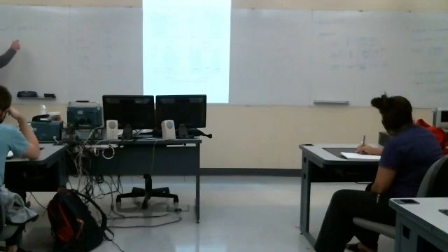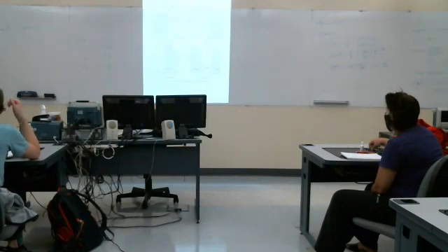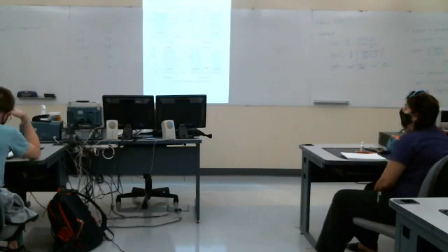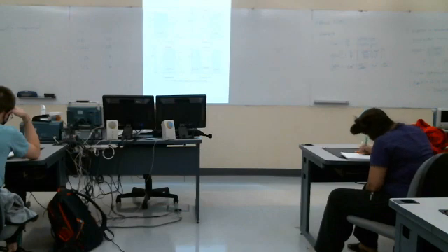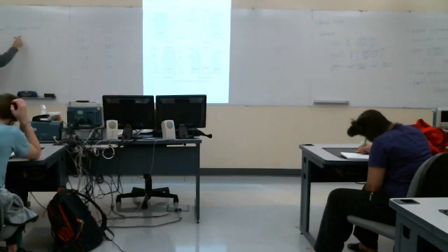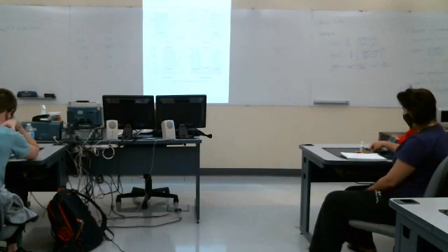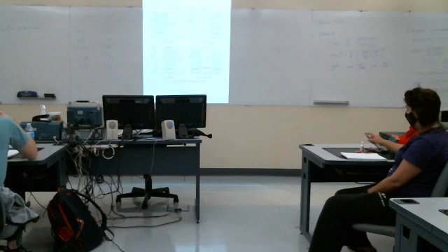So when omega is 10 times omega c, a decade above omega c, this will become 20 log of 10, which is what? It's 20. So this would be 20 dB. When omega is 100 omega c, what does that evaluate to? 20 log of 100.